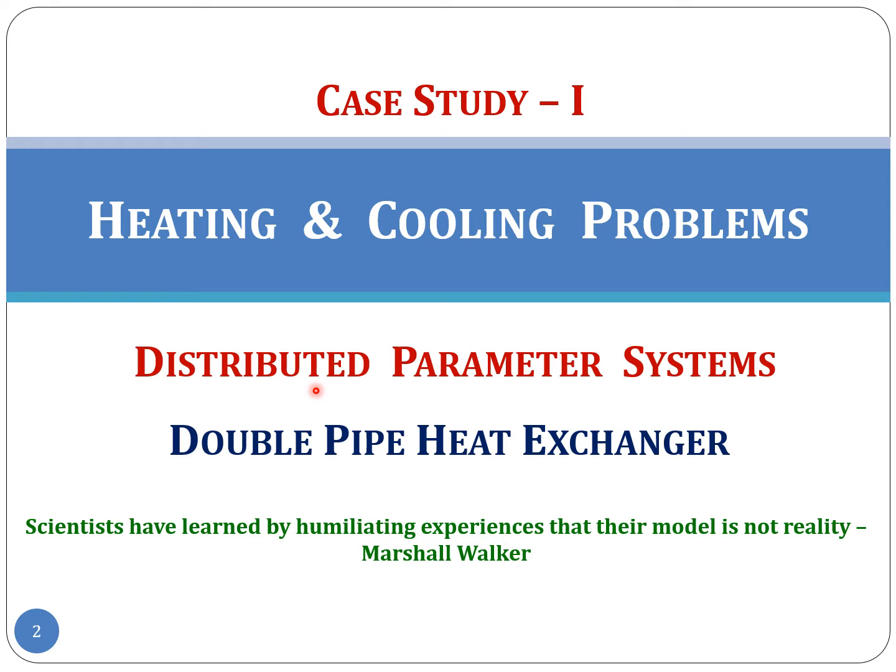And we will even discuss under what conditions such an approximation is legitimate, but we will consider that model of a double pipe heat exchanger. So in the first part we are going to have a distributed parameter system that is in one dimension. In the second part we will consider a distributed parameter model of the double pipe heat exchanger in two dimensions.